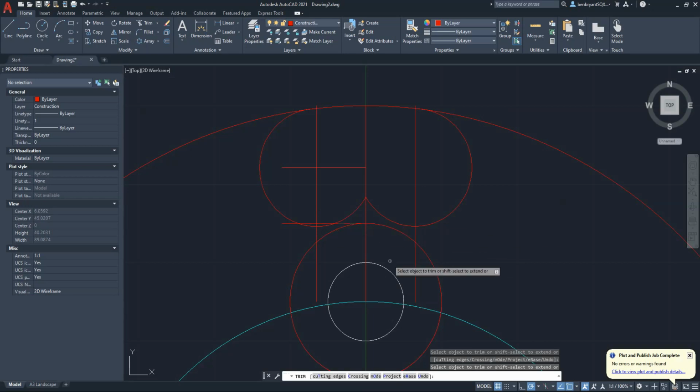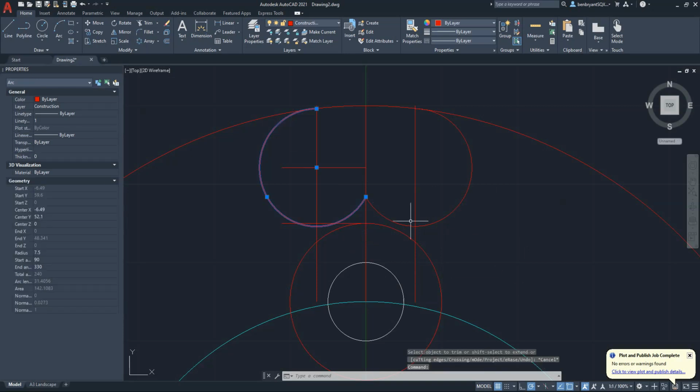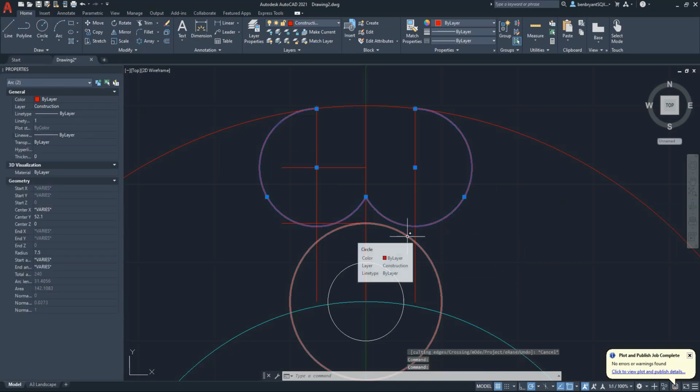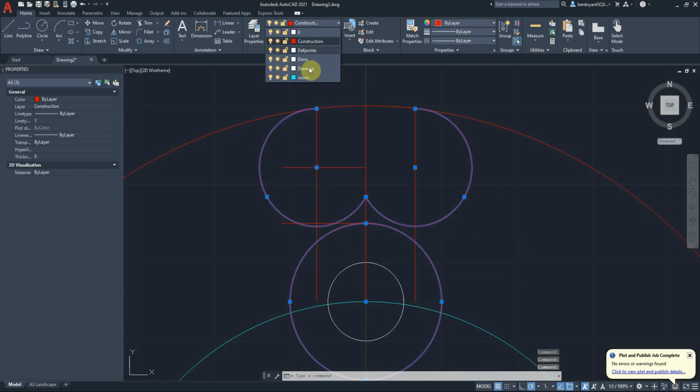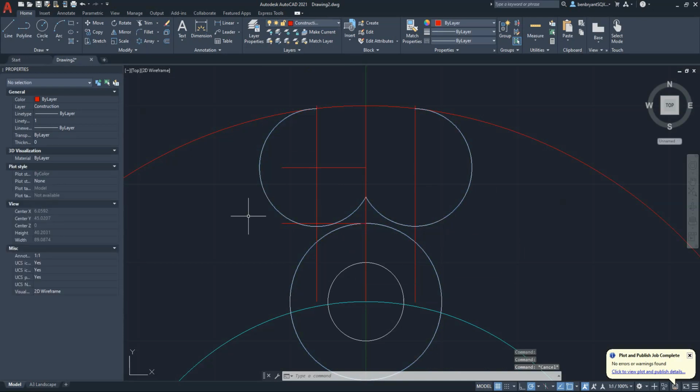So we have that part there, and what I'm going to do is convert that one back into my drawing. Okay. Now if I fill it in between this one and this one, I need to put the radius in first, so radius is going to be 10.